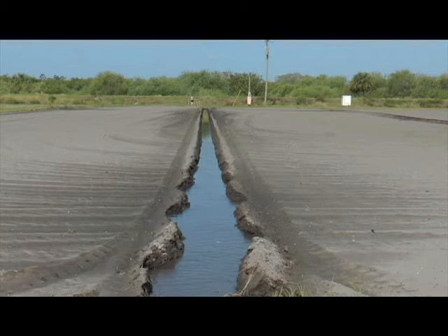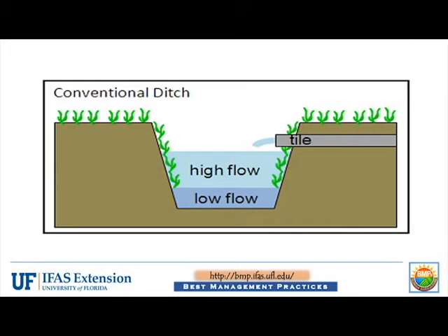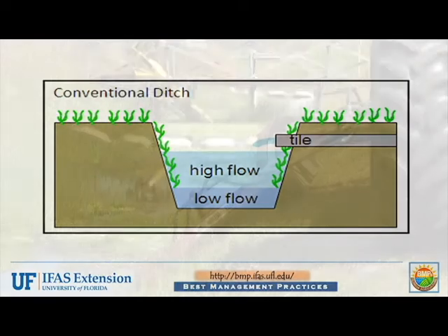The size of ditches will primarily depend upon the drainage characteristics of the land and the desired conveyance capacity of all ditches combined. Caution must be exercised when constructing ditch banks so that ditches will remain open. Ditch bank side slopes in very sandy soil should be constructed with a minimum slope of 3 feet horizontally to 1 foot vertically, or a 3-to-1 ratio.